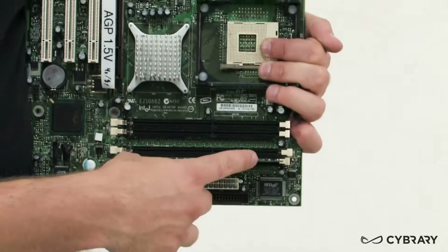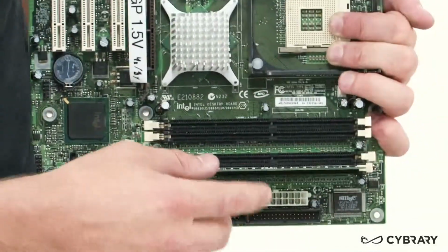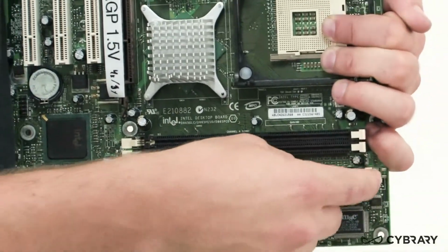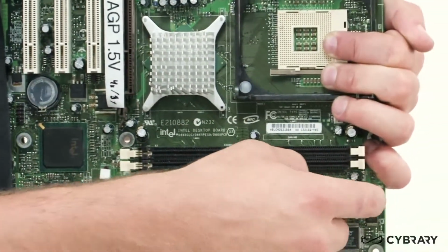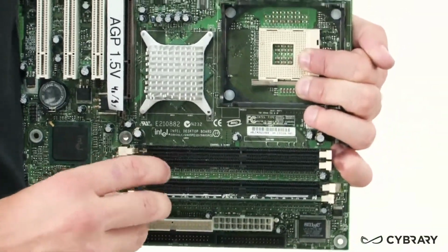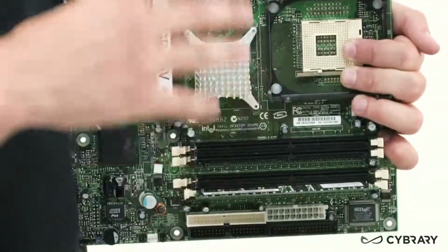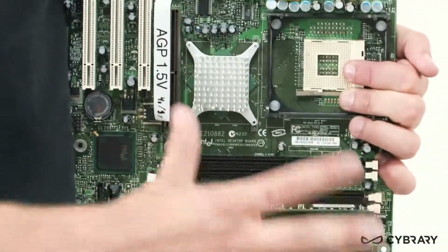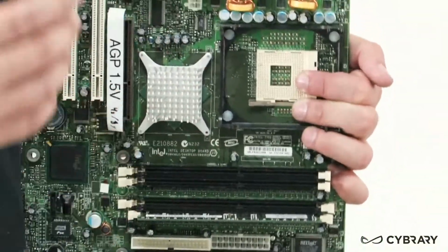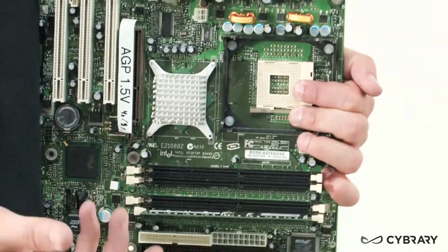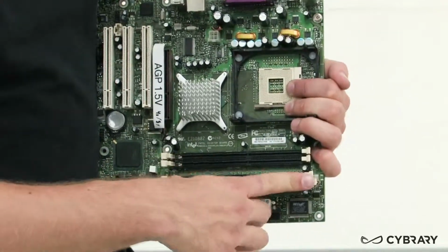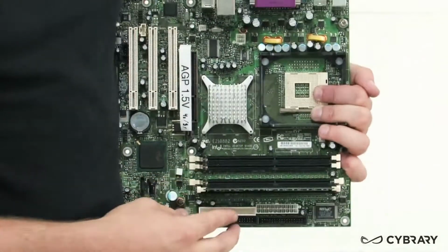Now, this one looks offset, and rightfully so, because it's not the correct card to go into this slot. But for demonstration purposes, I was finagling it a little bit. However, these cards slide into the slot and then are locked into place by the levers. Remember, on a computer motherboard, we never want to force cards into slots, because a lot of times, especially when we're working with small computer components like this, if we have to force something, it probably means we're going to break it. So we want to be gentle with cards, we want to be gentle on our motherboard, and we want to put cards in properly, like so.